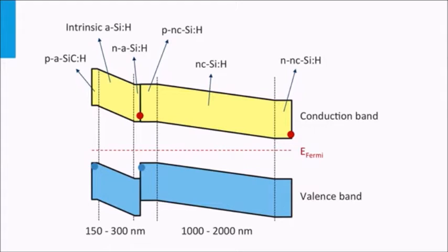Similar to the III-V multi-junction, the electrons and holes have to recombine at the recombination tunnel junction between the n layer of the top cell and the p layer of the bottom cell. Often, a very thin and defect-rich layer acts like a tunnel recombination junction here. Here, these electrons and holes recombine. Again, the total current density is equal to that of the junction with the lowest current density. It means that in an optimized multi-junction cell, all current densities in the various subcells have to be matched to achieve the best spectral utilization.